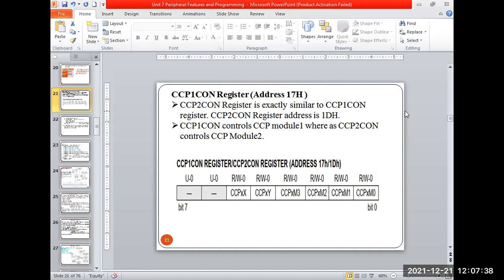So last lecture we have seen about the CCP module in the PIC controller, and that CCP defines capture, compare, and PWM generation. Out of that, we have done the first mode, that is called capture. Any transition going on in the clock cycle can be captured by storing that value in the CCPRL and CCPRH registers. So that 16-bit value can be captured from the timer values that we have seen from that block diagram.